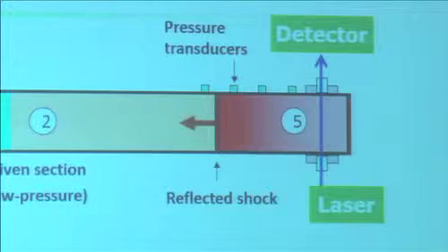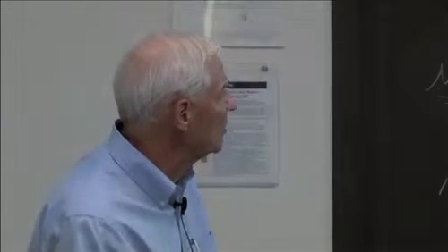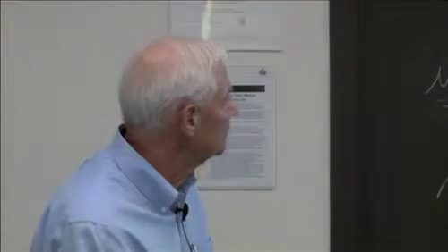The shock wave is very thin, and so basically it's a step change in temperature. A shock wave is actually a few mean free paths thick, but that's negligible for us. So it's basically a step change in temperature and pressure for this gas, causing it to begin to change. How does it change? Temperature changes. That means the rotational temperature has to change, the vibrational temperature has to change. Then the chemistry takes place, and temperature may change. So usually there's 1 temperature, but I'm going to show you an example where there's 2.